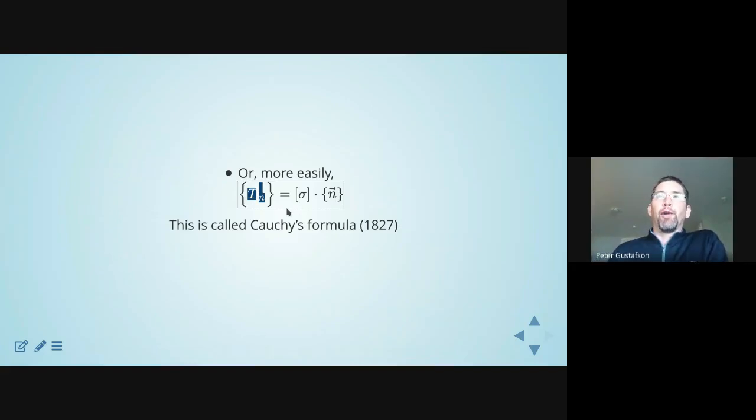Similarly, if we dot a rank 2 tensor with a rank 1 vector, we reduce the rank by 1, so we get a vector equal to a vector. Here now the sigma represents those 9 components. The n vector is the vector that's associated with the face. It's normal to that face, and this is now the exposed internal traction vector associated with that face.